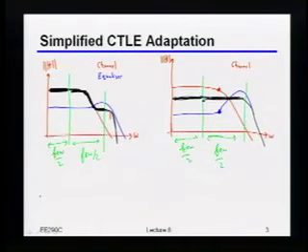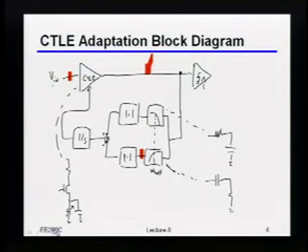Yeah. What about doing this in the digital domain after the...? Okay. There are versions which will turn out to do something similar, but remember, I've only got a single bit coming out of here. So in other words, if I actually see spectral differences in the bits coming out of here, that either means that my data is bad because I'm not sending white data, or it means I'm actually making mistakes.